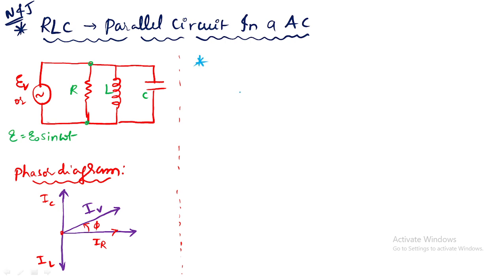Is it done? So if I take the capacitive side, because current will lead in this one, and I_C is greater than I_L, the current will automatically lead in this circuit. I take this line with green color, which is I_C minus I_L. Can you see this green line?